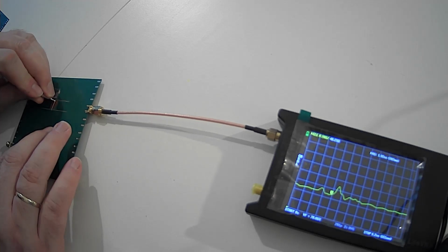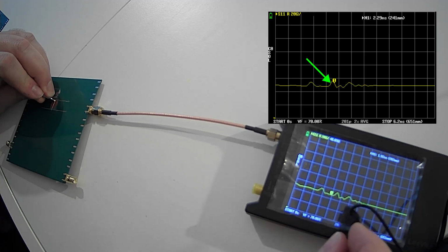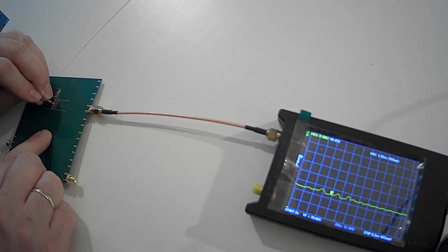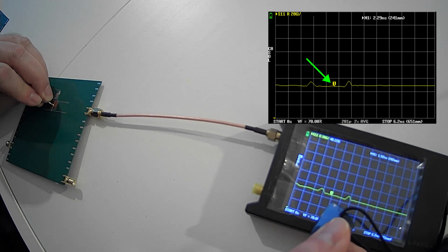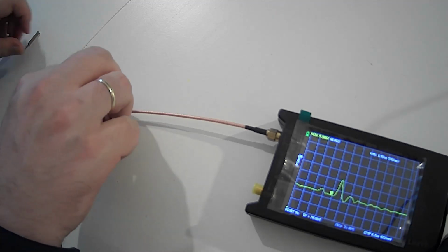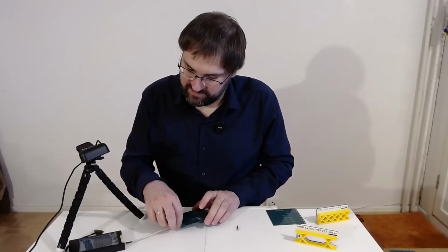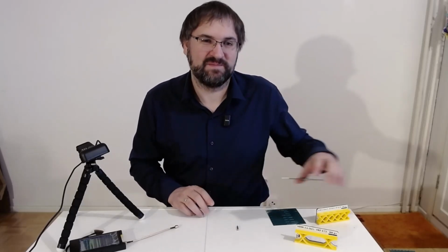So if I connect here, you can see there's still a small difference in the impedance, but if I put it right under the trace, you can see how it completely disappears, and so the return current can now travel its preferred way under the trace. I think that's quite cool that this can be done with a vector network analyzer, and see you next time.